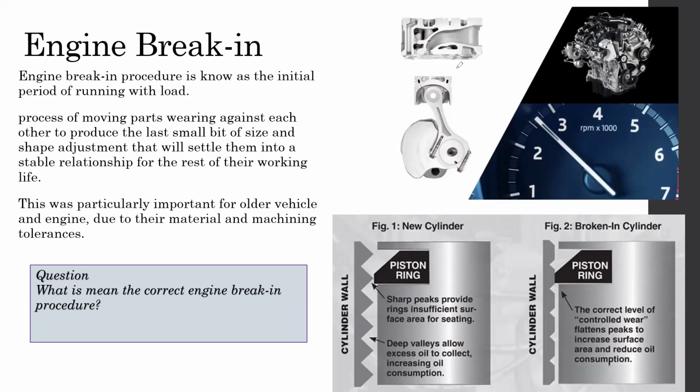Nowadays, because of the high quality control in the manufacturing industry, each and every engine has to go through a whole dyno process. These dyno processes test the engine: how much temperature it reaches, what stress levels the engine is getting, what the combustion pressure inside the engine is, and all sorts of things in addition to that. For this it runs continuously for about 15 minutes at high loads. Because of that, the engine breaking-in process is not that necessary for a brand new vehicle. But for an engine rebuild, it's always advisable to do it.